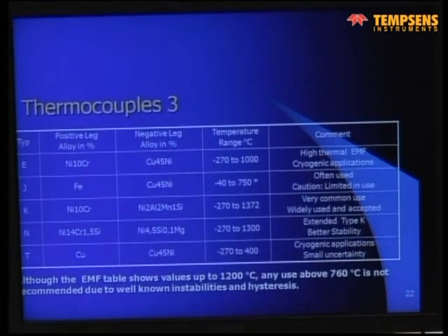So, for industries also it is suggested to go for type R in place of type S. Yes, stability is better, and the problems with inhomogeneities are lower. It is better. Unfortunately, the price is slightly higher because rhodium is, in most cases, higher in price than platinum. And so 3% more causes a higher price.